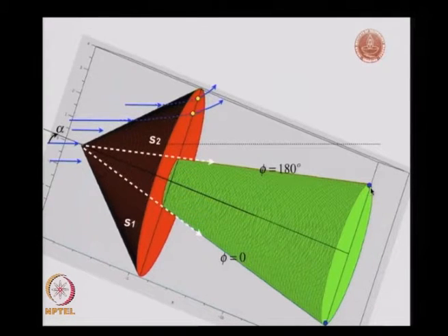That's all as far as the straight streamlines are concerned. That's it. Rest everything is curved. What do I mean by that? So like I said, you have the flow which comes in, and you have one streamline going right down at the phi is equal to 0 part of the cone. You have one more going at phi is equal to 180 degrees.